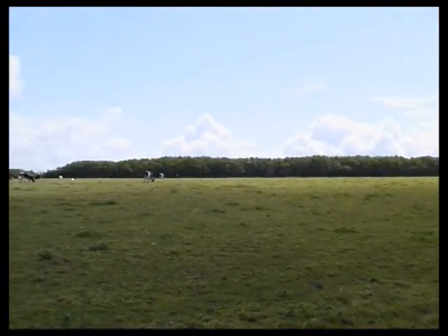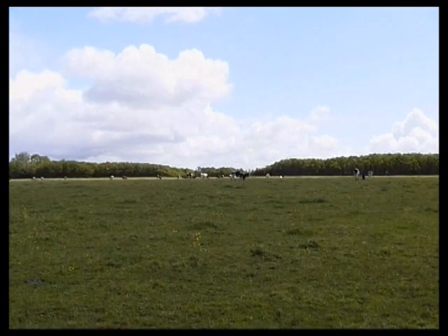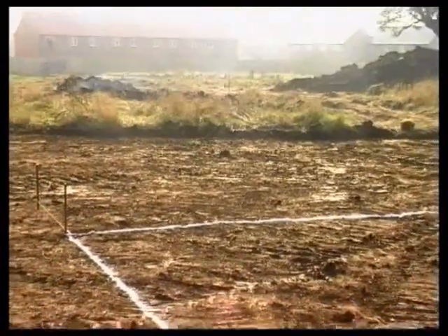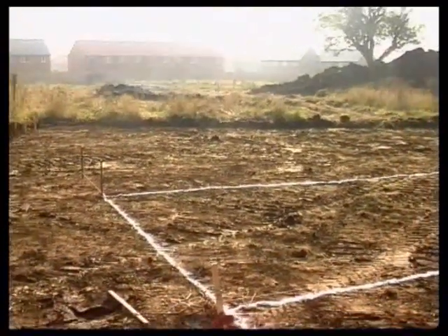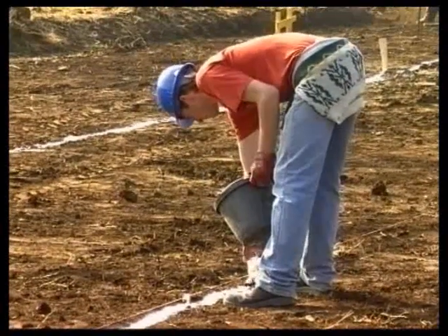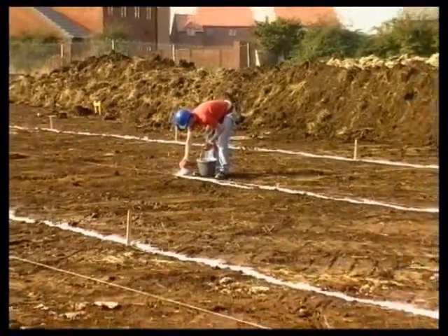Most houses are built with strip foundations, but whatever the foundation type, the first stage is to remove the topsoil, typically 150 to 200 mm thick. This organic material can be taken away and sold or stockpiled for future use. The centre line of the foundation trench is set out for the digger drivers.